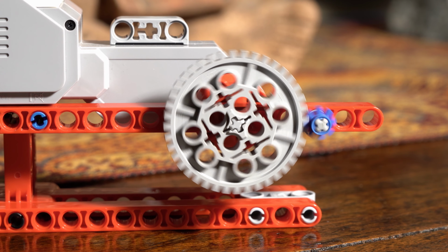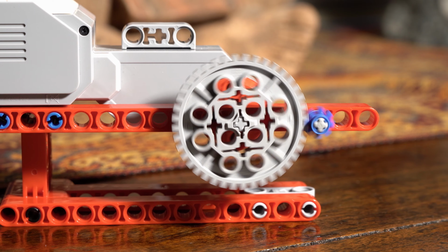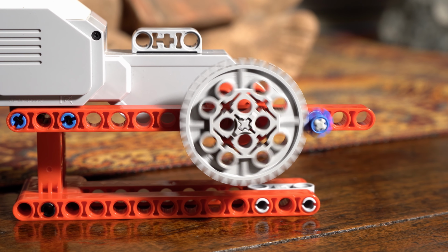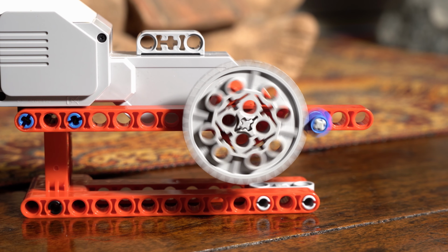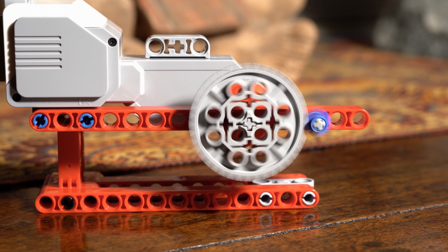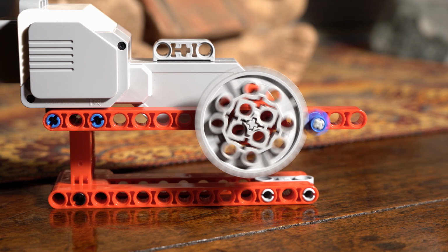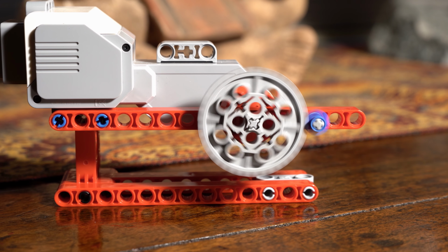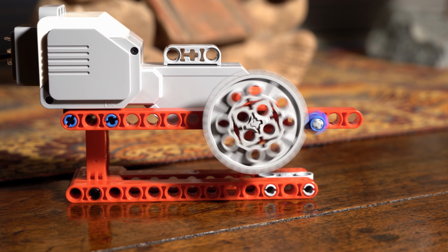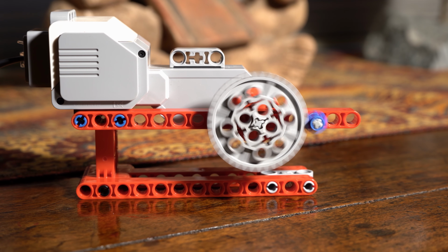For example, the largest and smallest Lego spur gears are 40 and 8 teeth, as shown here, so the simple gear train can only increase the driven gear speed by 500%. The Lego EV3 large servomotor has a maximum speed of approximately 210 RPMs, so a simple gear train with a 1:5 gear ratio can reach a maximum speed of approximately 1050 RPMs. So, if your Lego model requires 5000 RPMs, a compound gear train can achieve this.